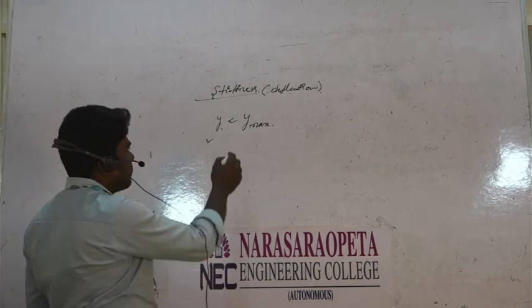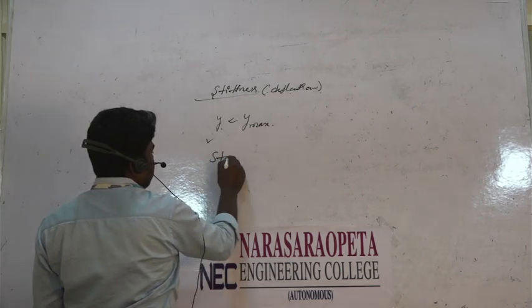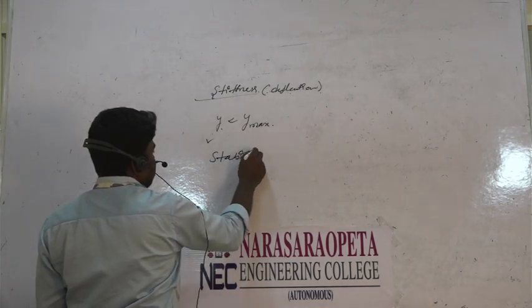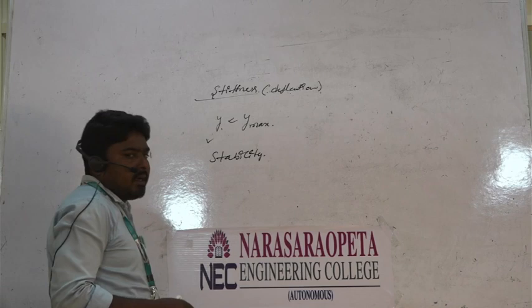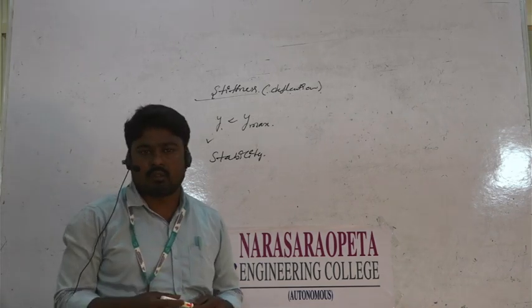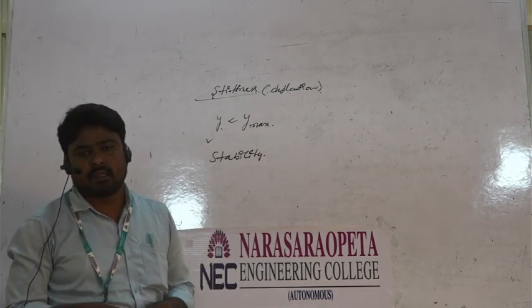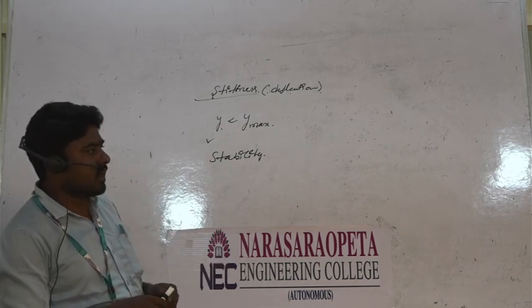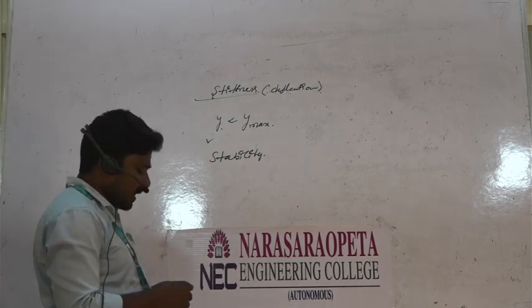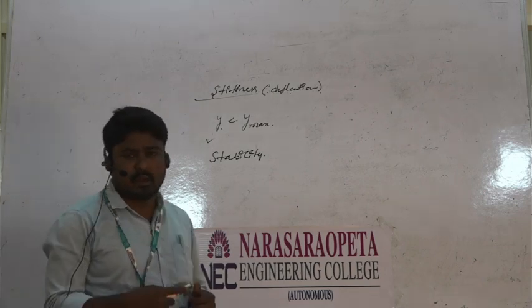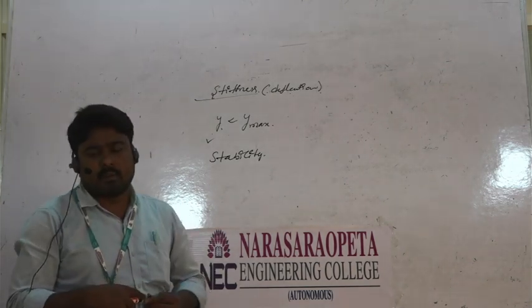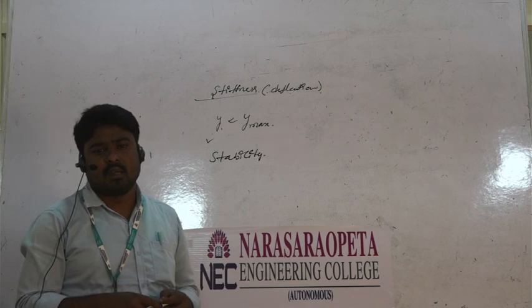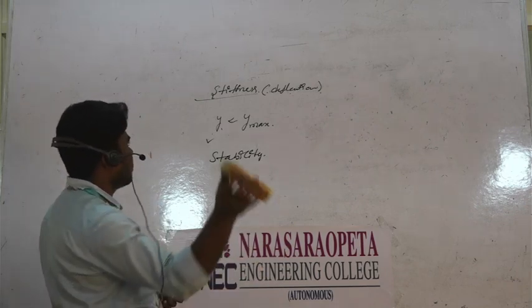Similarly, the third requirement is stability. We discussed stability in columns and in direct and bending stresses. In most cases, columns are axial compressive members, and direct and bending stresses develop in dams and retaining walls under different conditions.